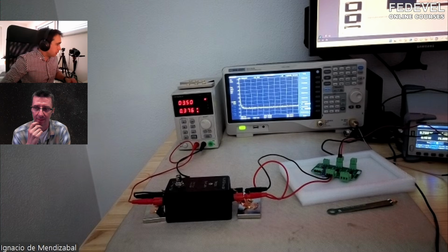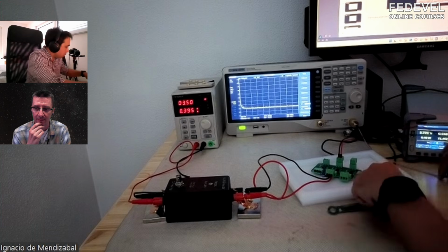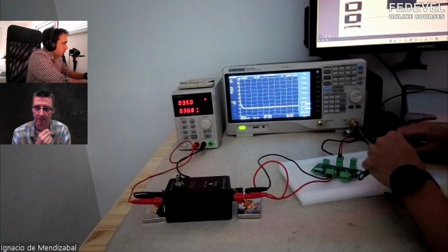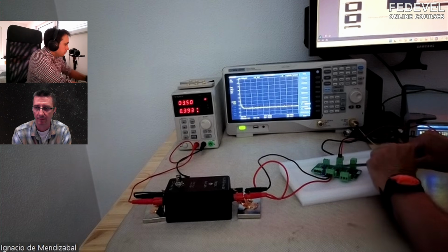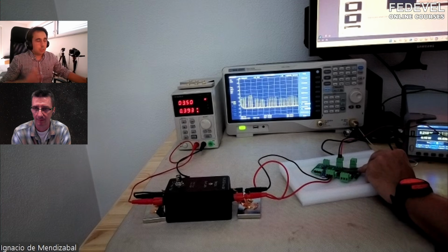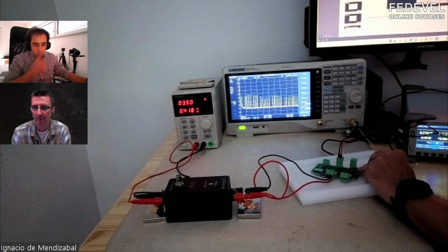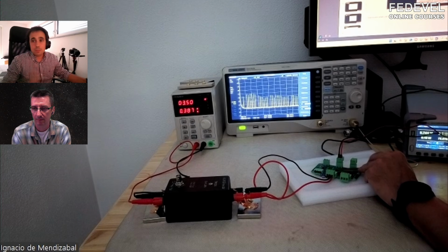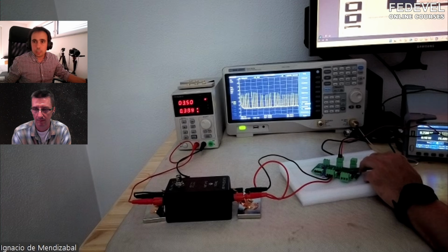So what happens is, and this I can measure, that here we can see it. So yeah, it's noisier. It's because of two things. When you are looking for noise problems or noise issues, you need to think about two factors. One is the frequency, so it's the switching frequency. And second, what is the rise time and fall time of your signal?